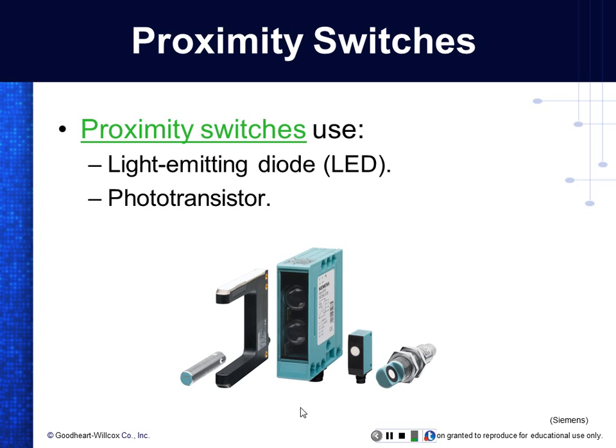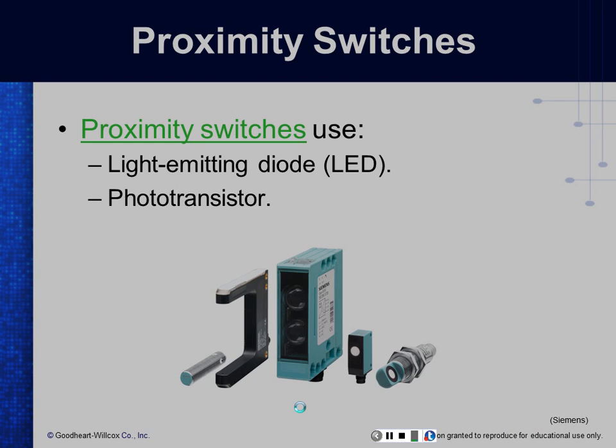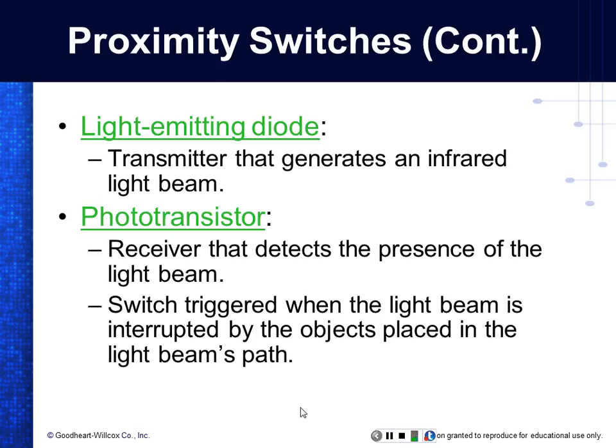If nothing's close to it, it doesn't work. Or it can be set up reverse, where if something's close to it, it doesn't allow it to work. So a lot of the robot cages have proximity switches in there, or proximity detectors of some type. And so when you get near that proximity sensor, it knows you're too close to the robot and the robot will not work.